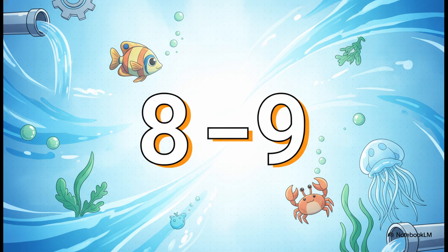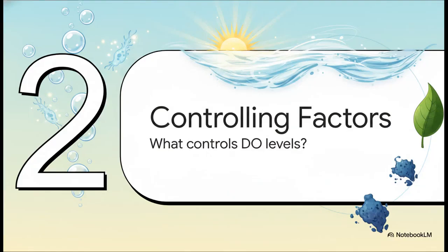When we measure this dissolved gas, we typically use milligrams per liter. And the magic number we're often looking for is right around 8 to 9 milligrams per liter. This specific concentration indicates a really high-quality water condition. At this level, natural ecosystems are absolutely thriving, aquatic life is fully supported, and if we're talking about an industrial context, it indicates an excellent, highly sanitized wastewater treatment output. But here's the thing. Water can't just hold an infinite amount of oxygen.